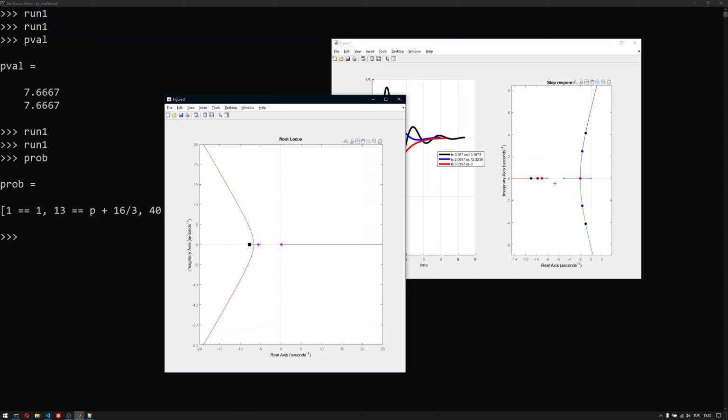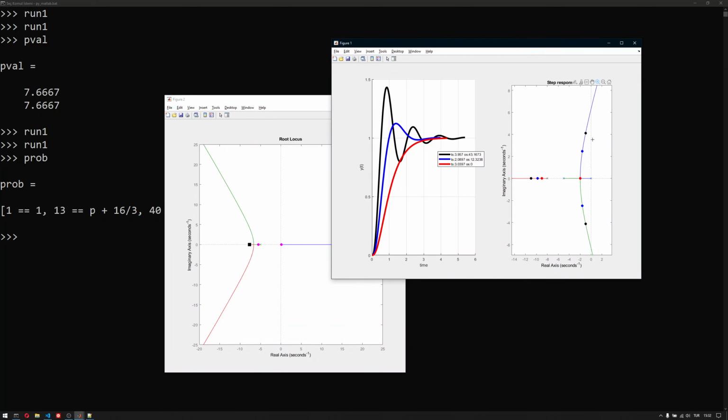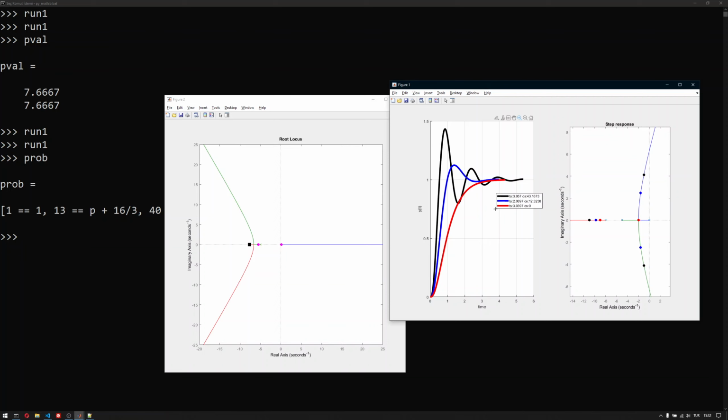The zeta omega n pair should form a complex conjugate pair in order to be able to use the settling time and overshoot in order to assign these to the closed loop using a P-type controller.